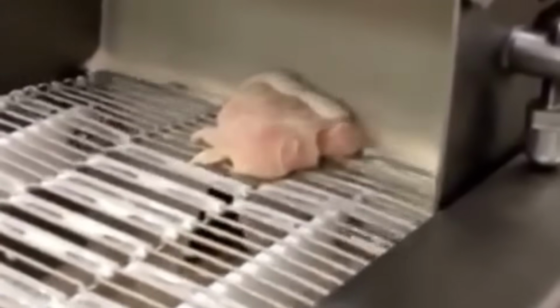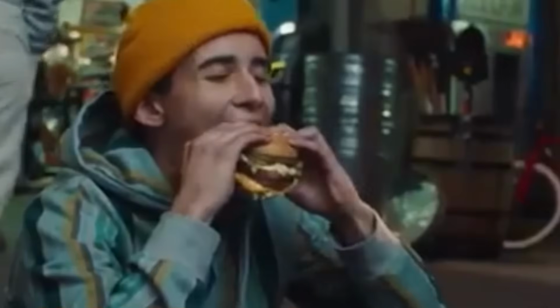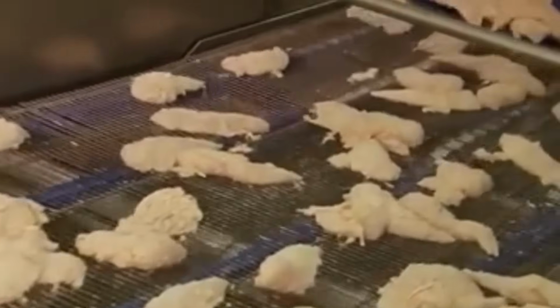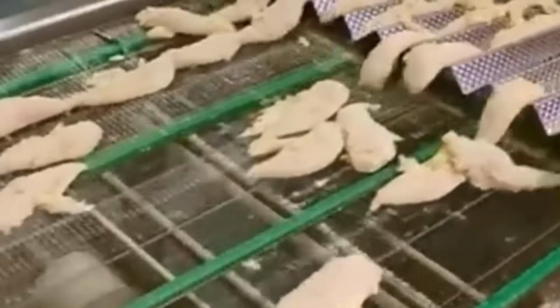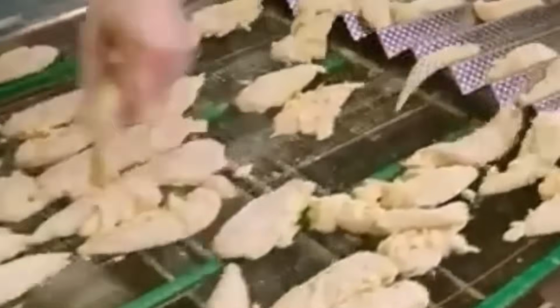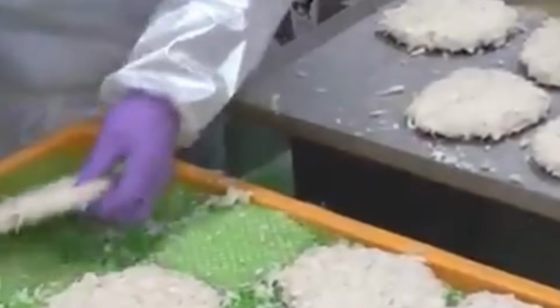The upper platen is heated with embedded electrical elements and lowered using pneumatic pistons. The bottom platen remains fixed and maintains a set temperature through thermal sensors. Cook time is controlled by belt speed and platen temperature. Average dwell time for each patty is between 100 and 120 seconds, depending on thickness and grill load.